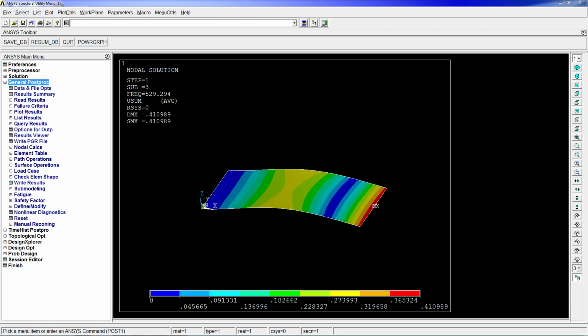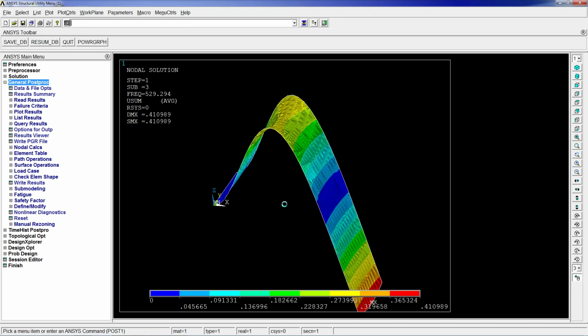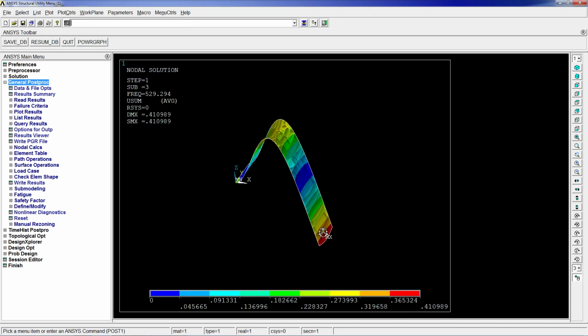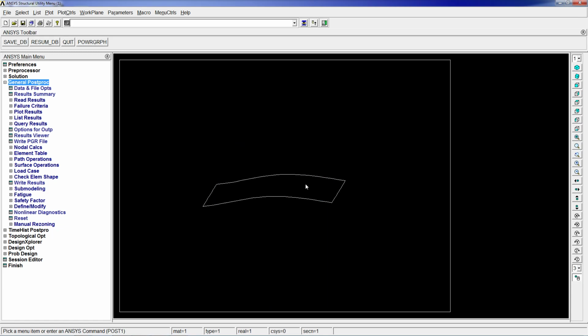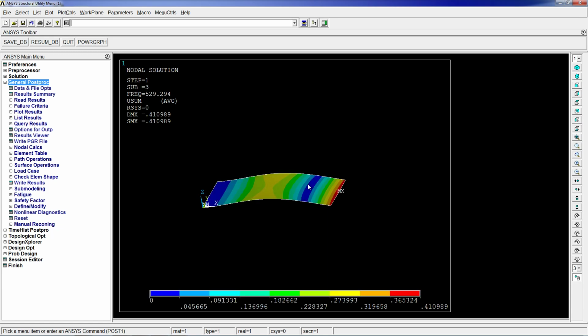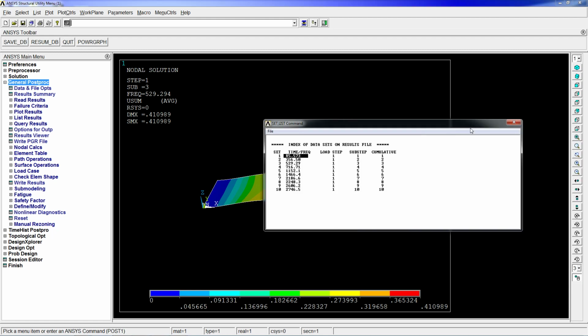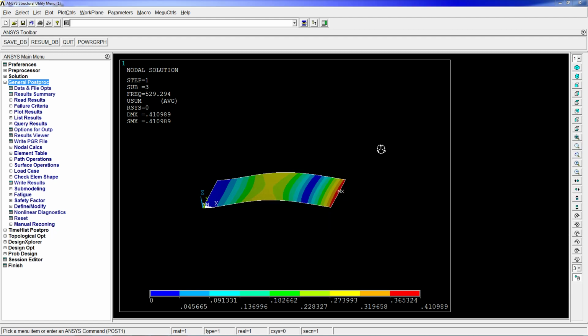And also the deformation values, for example, here, we're going to look at this scale, 1. As you can see, the end of our plate is deforming 0.41 meters. And that could not be possible. That is extremely low. We're going to go back to this scale, auto. These values are obtained from calculation because we're obtaining the main vectors, the eigenvalues. So they only are good for evaluating the frequencies and the shapes. So what we're going to do today is perform a harmonic analysis.